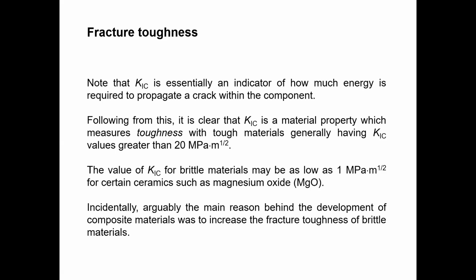Incidentally, arguably the main reason behind the development of composite materials was to increase the fracture toughness of brittle materials. I told you this exceptional case. Sometimes a brittle material, if combined with a ductile material, even with a high portion of brittle part, the KIC value can be enhanced. That is what composite means. Normally a composite is not a natural thing; it is an artificial thing.